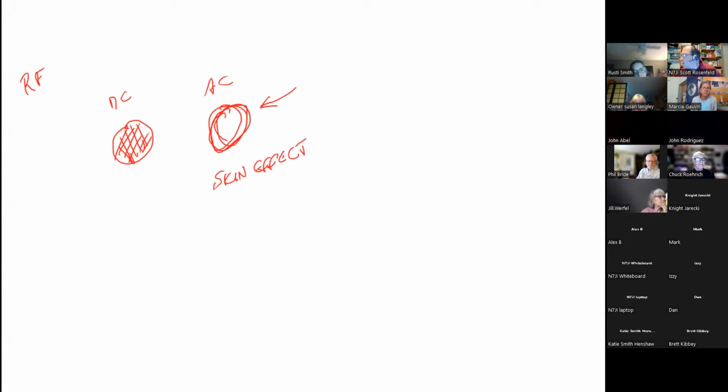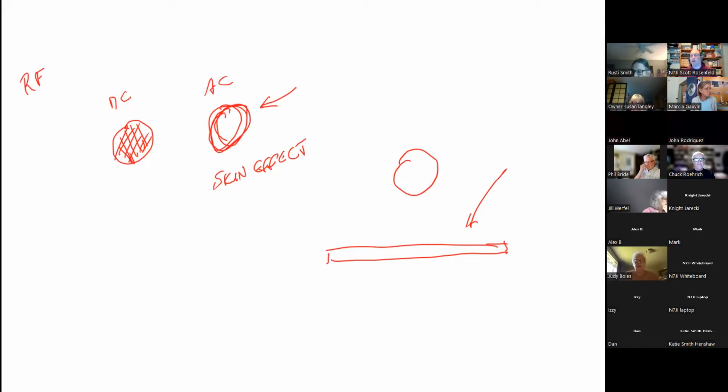So since it likes to flow on the outside, we're basically just looking at this as the surface area. If I have the same amount of copper, I can take a piece of wire and make it in the shape like this, or I can take it and flatten it out and make it like this. Which one works better? Which one has more surface area? The flat one. So the flat strap of cable has a much lower resistance, or much lower impedance, to RF energy, to AC. And that's why most of our grounding, we use flat strap instead of round copper wire.